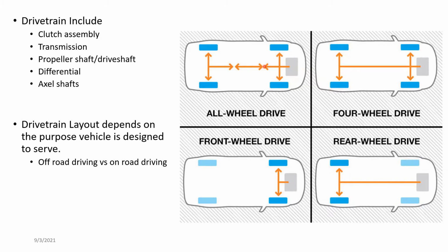These two can have similar dynamics. Especially, the all-wheel drive system can be designed to have the same characteristics as a rear-wheel drive system by changing the gearing ratios between the front and rear. Even simple solutions like that can be used. But then there are electronic control modules.